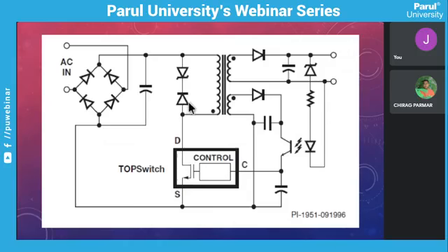It is a very fast recovery diode, UF4007, and a TVS diode. A TVS diode is very well known for high reverse voltage and efficient power dissipation. So it drops that remaining amount of energy. A TVS diode and a fast recovery diode are used as a snubber circuit. You may very well know that in a DC-DC converter, this is a type of snubber circuit.